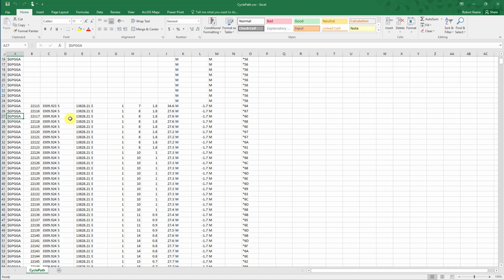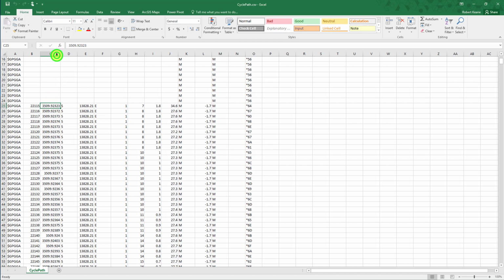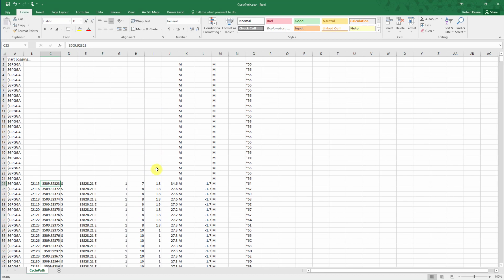So normally it sends what we call an NMEA string, and there's different types of variables that can be stored in here, and we can see that this one's picking up the GPGGA sentence. So here's our coordinates, and as you can see, we need to divide them by 100. So it multiplies by 100 in order to not need to have as many decimal places, because that becomes quite hungry for data.